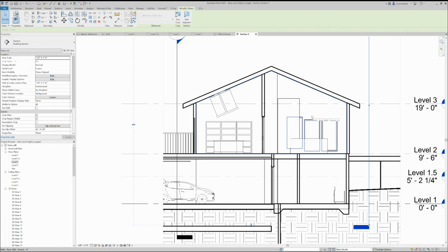So I need to draw and remember all these walls are stuck on the roof because at the beginning of this little lesson, I went into the model, selected all the walls, selected the filter, made sure that only walls were selected, and connected them to the roof because there are no ceilings in here. So you need to draw a ceiling in here.